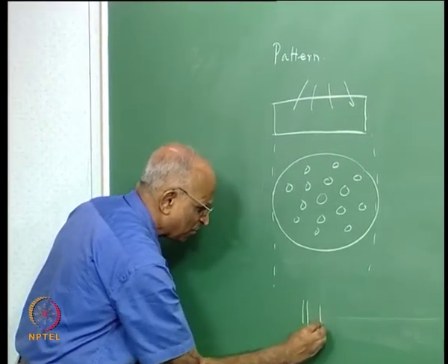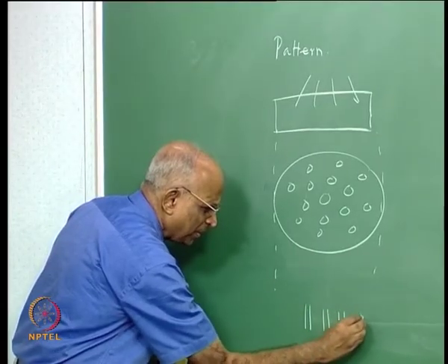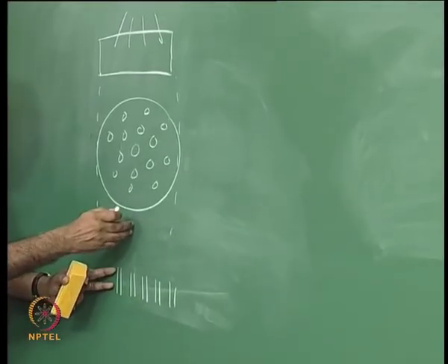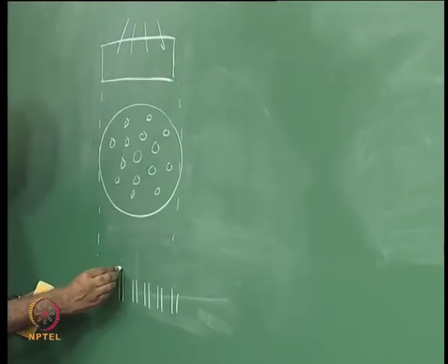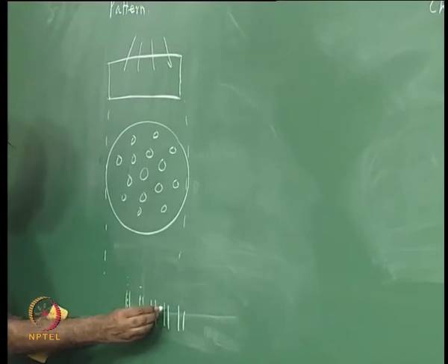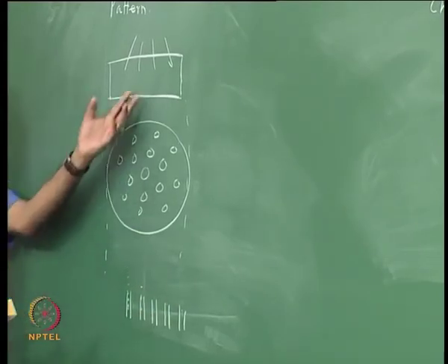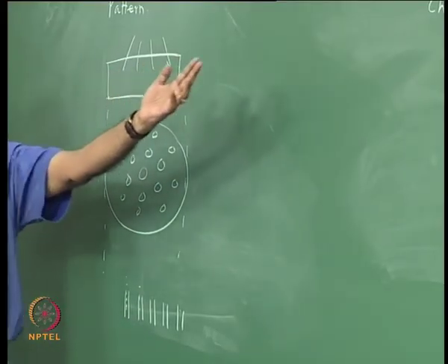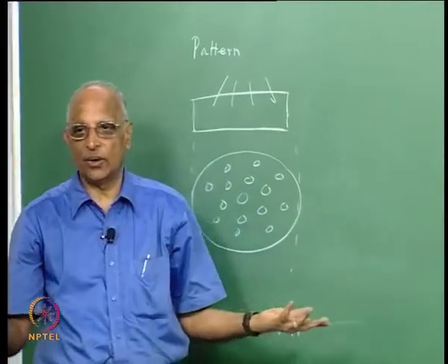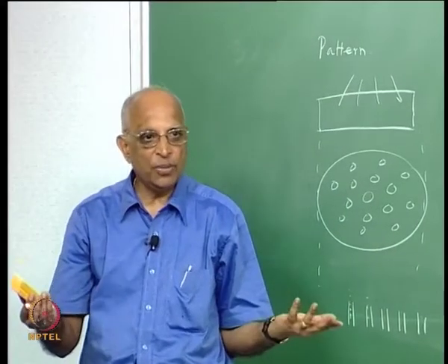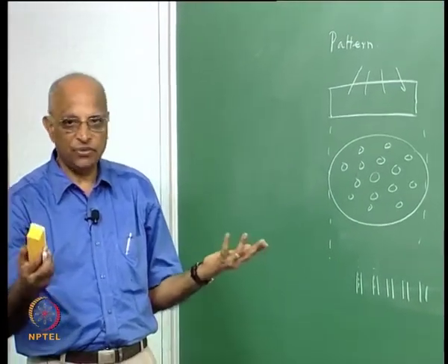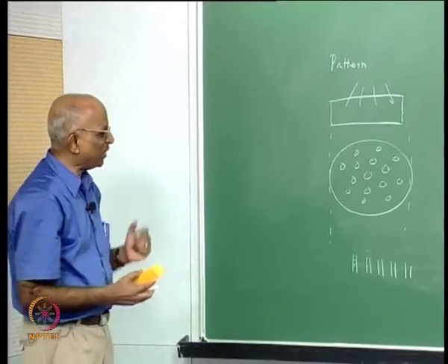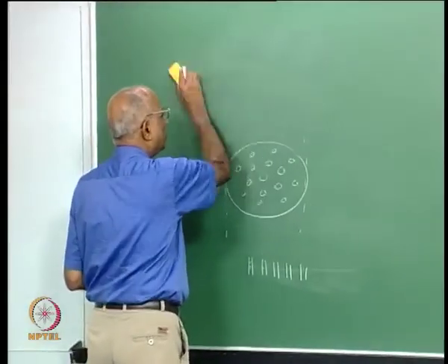I put a series of test tubes all along, a little bit away in the 3-dimensional zone, and now I collect the mass of the fuel and mass of the oxidizer at the different places. That means I can study the pattern formed by the injector, and this is what is used to calculate the xi dot. Once you know xi dot, I can find out the non-uniformity parameter and the efficiency due to the non-uniformity.